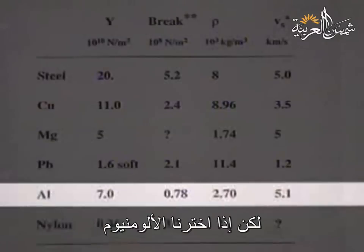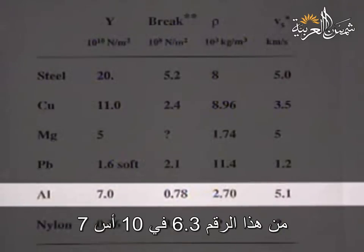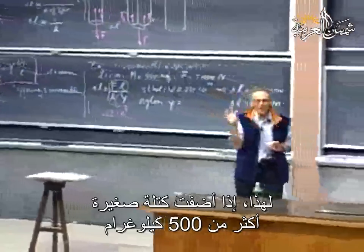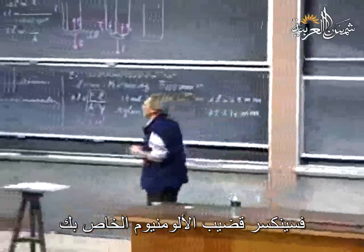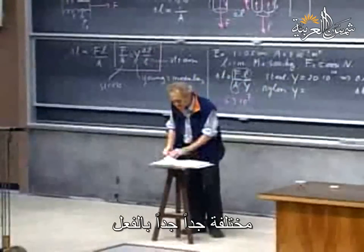However, if we made the bar out of aluminum, then you're very close to this number, 6.3 times 10 to the 7th. And so if you add a little bit more mass than 500 kilograms, your aluminum bar would break. So you see the properties of these metals are very, very different indeed.